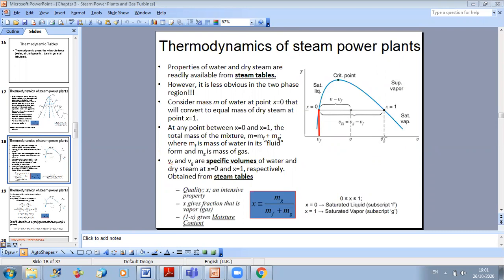Okay? It means there is no liquid anymore. If you have any, this is why, because we said here quality is 100%. So X is equal to 1. This corresponds to the vapor state. Now, if I give you any X in between, if I tell you X equal 90, you apply the formula. You can say there will be liquid and vapor. So there will be a portion of vapor, a portion of fluid, and then you apply the following rule to find the